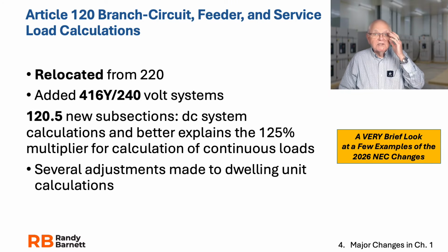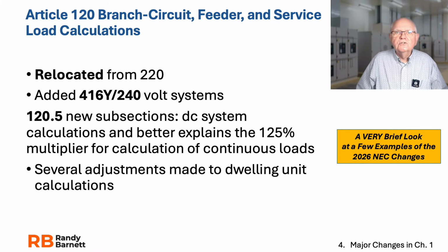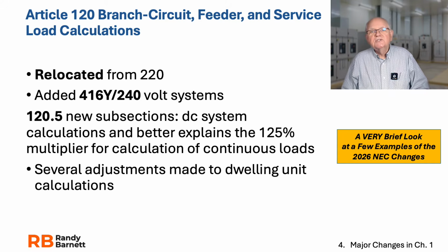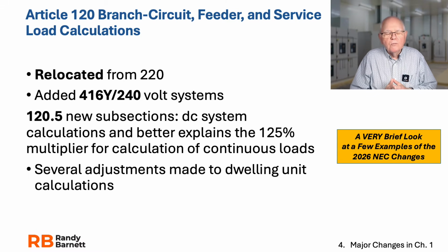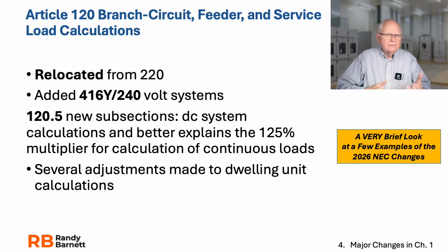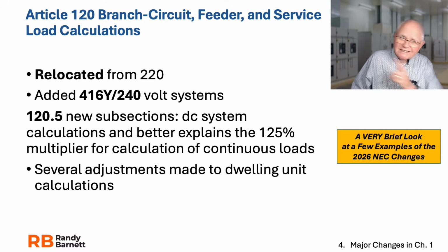Article 120 we said was relocated from Article 220. It's our branch circuit, feeder, and service load calculations. We still do calculations. There have been some changes. There's a new subsection on DC, and we see this throughout the code, right? We have more and more DC systems being installed, more and more DC power out there. So we see more and more information in the code, new sections, subsections, and so forth throughout the different articles referring to DC. So pay attention to DC.